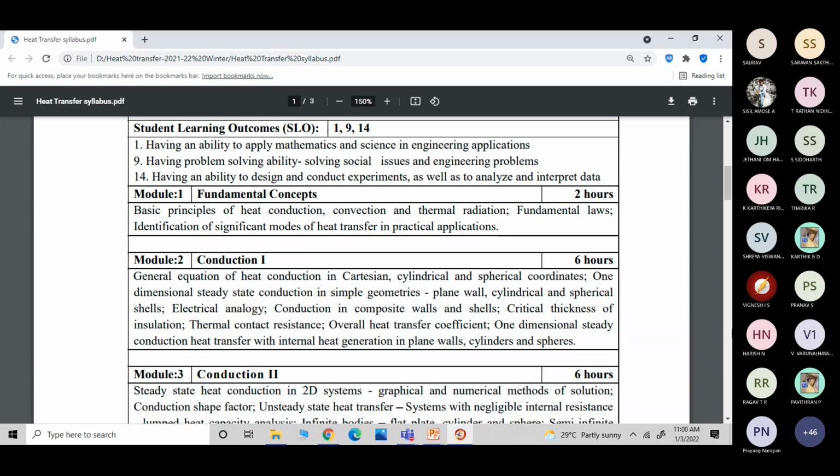Why do the cables burst? Any idea? Because the surrounding temperature is also high, and thermal expansion. Due to resistivity, there will be increasing temperature. Both combined put thermal stress, and since the insulation will expand, it will burst.